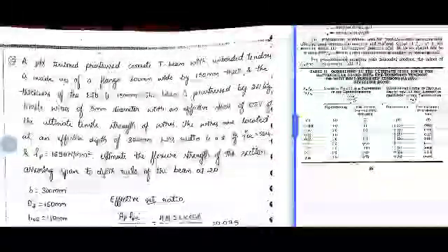So here it is given as post-tensioned unbonded tendons, that means it is the unbonded case, and in the question it is given T-beam, it means flanged section. So unbonded flanged section, it is case number 4. The flange width is 300 mm, flange thickness 150, web thickness 150. Here AP is not given, we need to find it out.